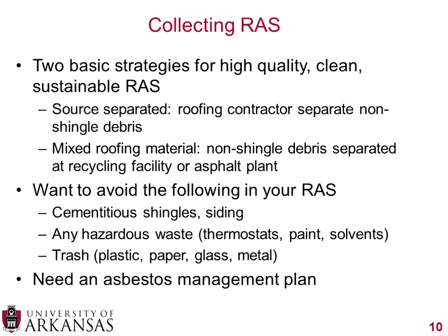It's not like they're taking the asphalt cement that we use in the paving material and just putting it on the roof. They have this extra step of air blowing it because they want the asphalt cement to be stiffer on a roof. They don't want it to be able to move at all like we do with flexible pavements. So they air blow it, which accounts for that stiffening effect.